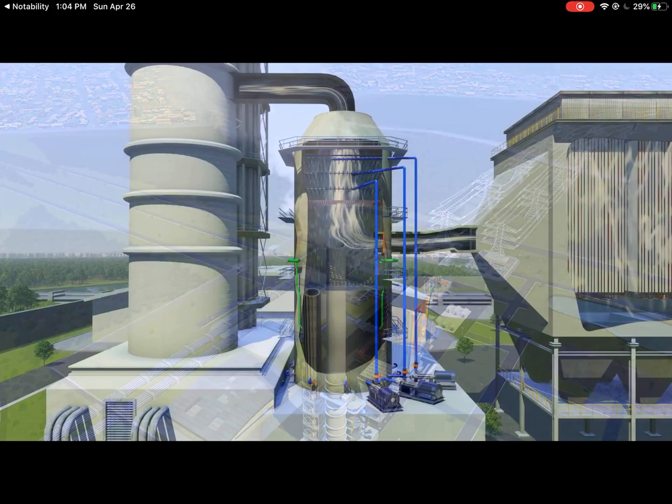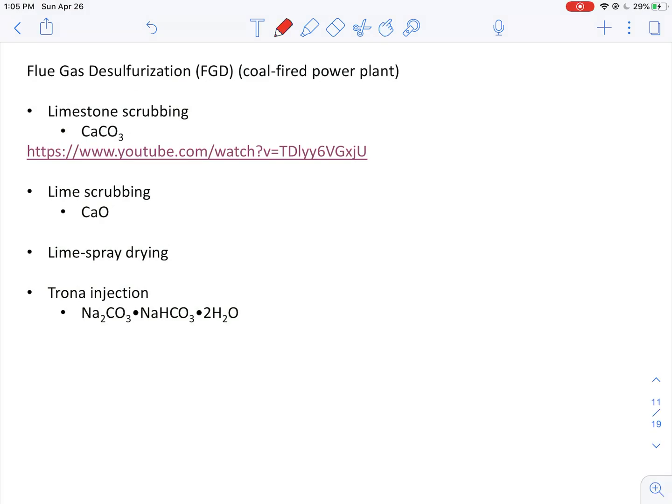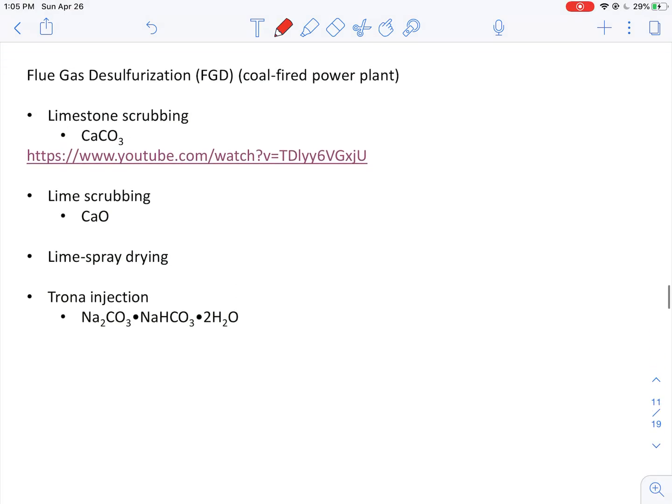So that's why we use this particulate matter removal process first to get rid of the particles, because this process will not affect the gas pollutants, and then introduce the gas into the scrubber to remove the sulfur dioxide. If we reverse this order, then the ESP probably wouldn't have that much significance, because many of the particles would be removed in the scrubber process. Okay, so let's go back to the contents here. People use this scrubber to remove the sulfur dioxide in the coal-fired power plant process.